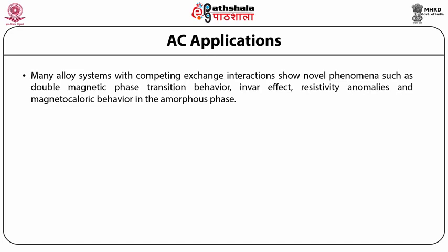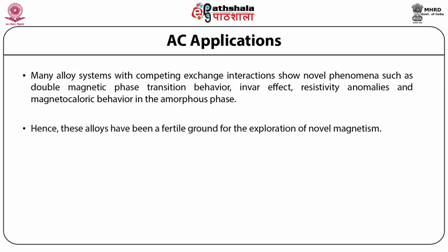Furthermore, these alloys in nanocrystalline state exhibit outstanding soft magnetic properties such as ultra low coercivity, high saturation magnetization, and high permeability. Hence, these alloys have been a fertile ground for the exploration of novel magnetism. It is well known that the general composition of such alloys is LTM-ETM-M, where LTM is generally body-centered cubic BCC Fe in the range 50 to 93 atomic percent. ETM typically consists of zirconium, niobium, hafnium, etc.